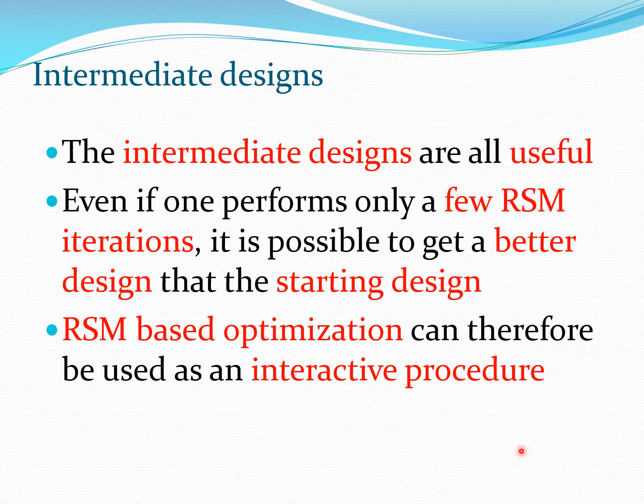Now, one of the advantages of response surface based designs is that any designs you obtain during the process are all useful provided they satisfy the constraints. And sometimes if your method works for a few shots and then it has some problems in terms of constraint resolution or in terms of convergence, you can still get a better design than the starting design. And therefore, several times this response surface based optimization can be used as a procedure where you play around with the actual code which you have, you develop these response surfaces, maybe you take 3-4 sequential runs of the response surface and then you get a good solution.